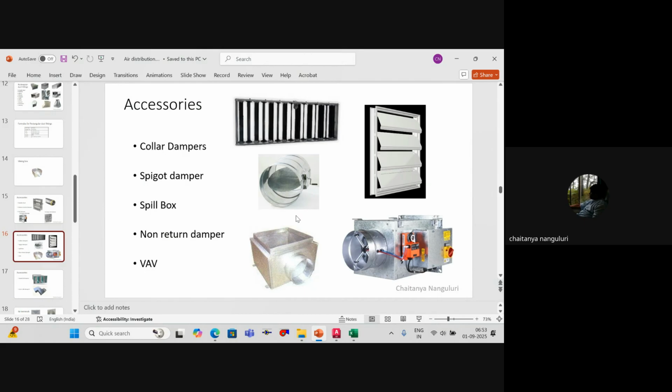Continuously, you'll get noise because it has to work against the gravity, right? So air will continuously hit, number one. Number two is there will be certain leakages as well because of the gravity type, because it should flow freely. So you'll have certain gaps between the body and this blade. Because of that, I generally don't prefer this kind of gravity type. I'll always prefer the actuator model, though it's a bit expensive. Understood?